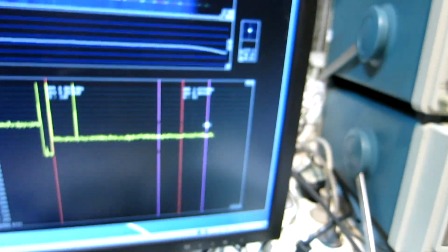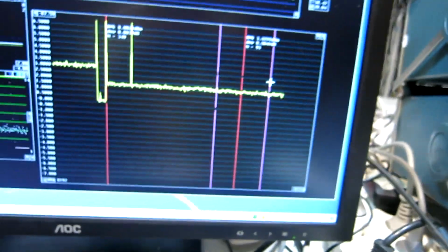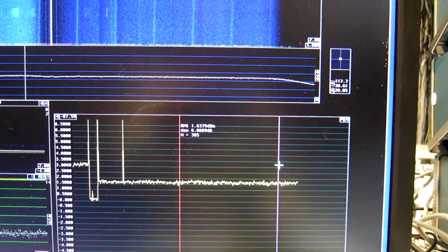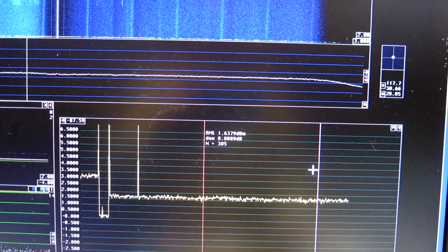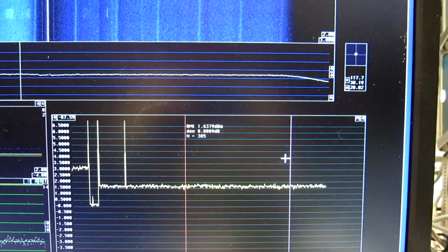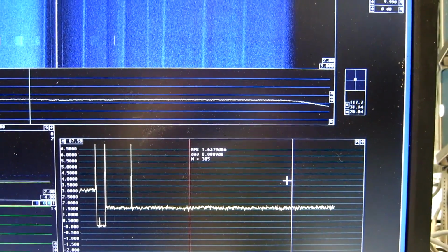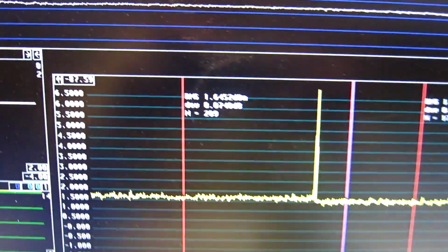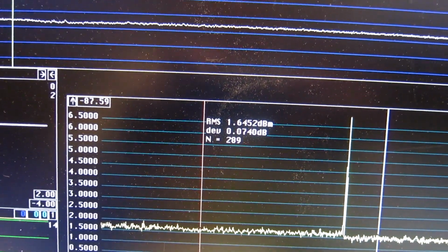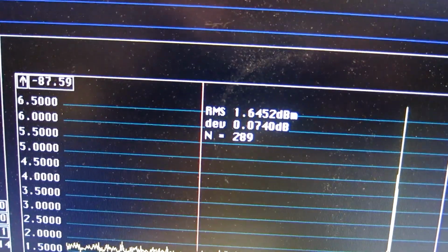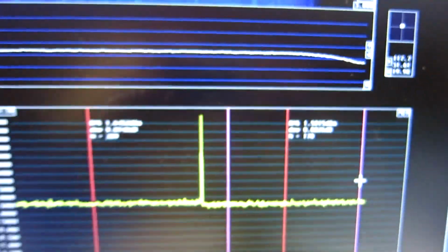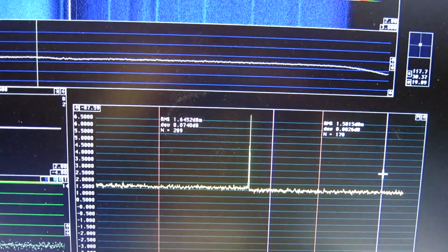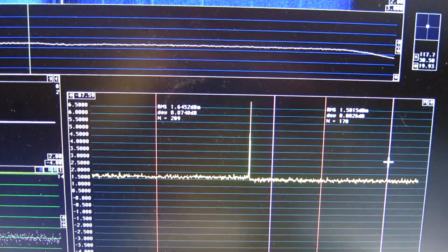And the noise floor I see at 50 kilohertz on the side is 1.64 dB above the noise figure of 8 dB. I have disconnected the feedback loop. That makes a very small difference, 0.15 dB, from 164 to 150. It means that it is not modulation of the carrier, it's the white noise from the transistors.